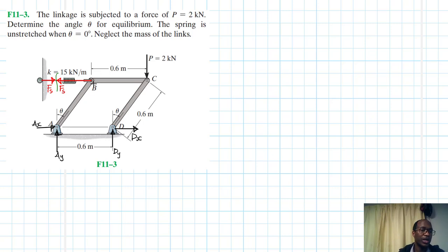At B we can apply a translational, at C a translational, at D a rotational. So we can apply it at any point. It doesn't really matter where you apply it. The solution comes out the same regardless of where you apply the displacement. After you've applied the displacement, then you draw the displaced or deflected configuration of that particular system.